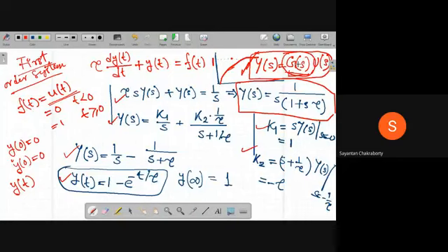So in this way, you can obtain the response of a system just by multiplying the input in the Laplace domain to the transfer function in Laplace domain. So this concept of transfer function will help to study the response of a system under various input conditions very easily. I have an initial idea about the response.